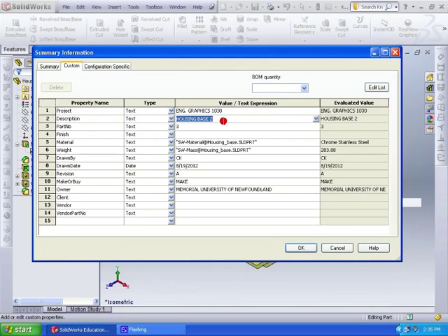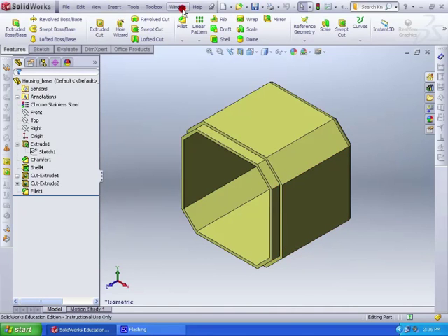And when you look in the title block, which we'll do momentarily, you will see where all of these fields are being entered. I also have the part number, so I'm typing in the information here, and that text will show up in our title block. So I'm interested in editing 1, 2, and 3. I'm also going to type in my initials, drawn by, so item 7, item 8, the date, and that's it for editing those fields. Once I say OK, those fields will be saved.